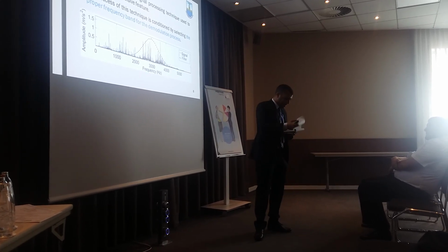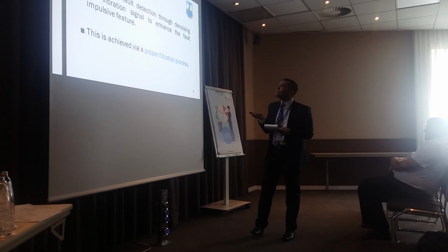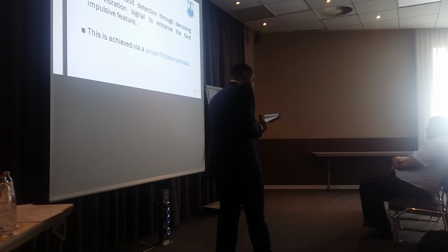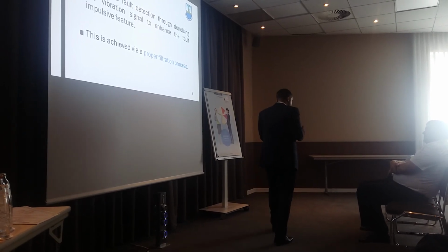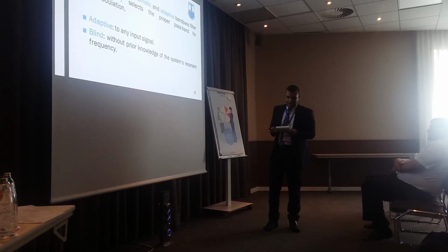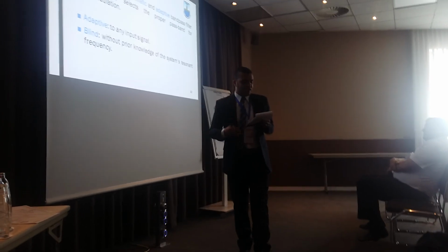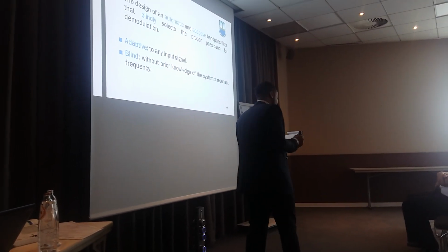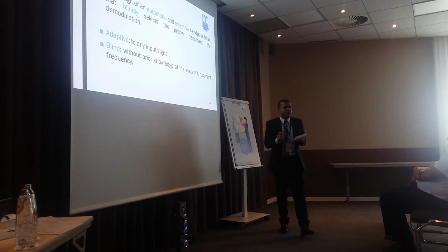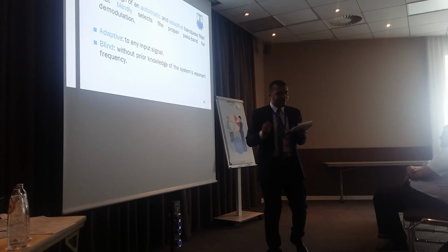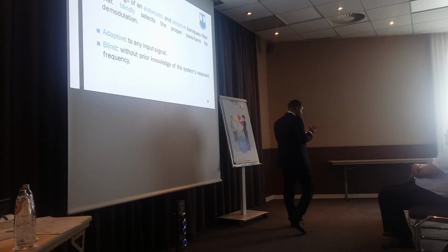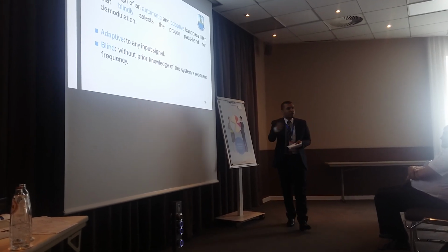So the objective of the work is to detect small faults early through denoising the vibration signal to enhance the impulsive feature. And this is achieved by proper filtration. Based on the objective, the developed methodology was the design of an automatic and adaptive band pass filter. Adaptive means that the filter can adapt to any input signal. That filter can blindly select the proper pass band for demodulation. And blindly means without prior knowledge of the system's resonant frequency.